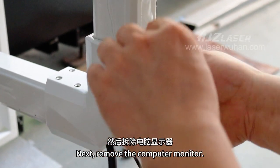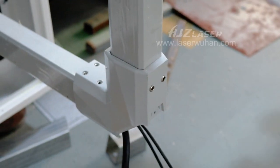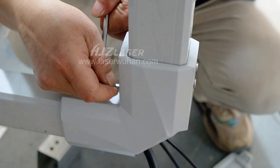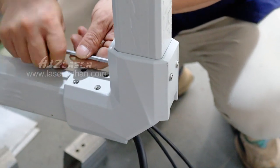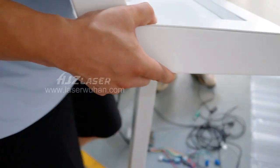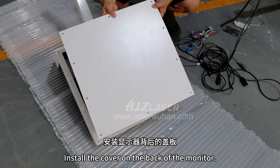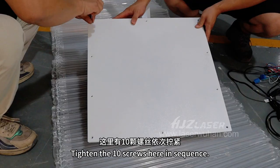Next, remove the computer monitor. Unscrew the 4 screws here. Pull it upwards. Install the cover on the back of the monitor. Tighten the 10 screws here in sequence.